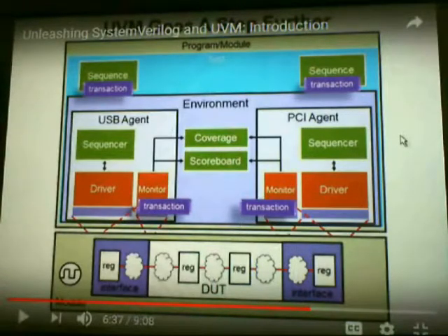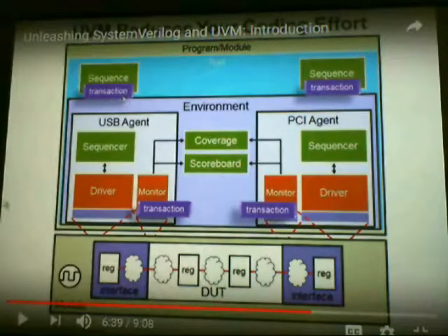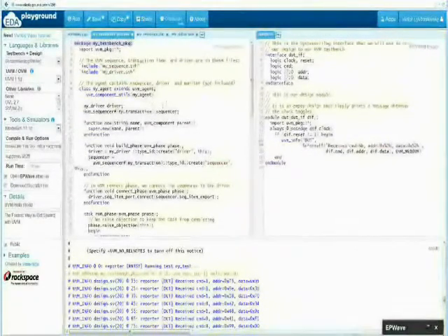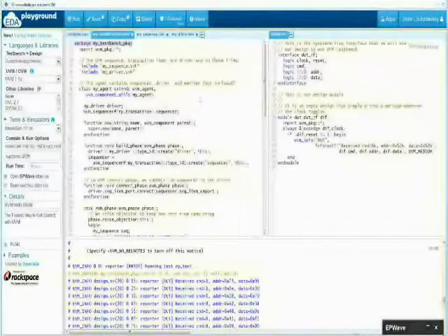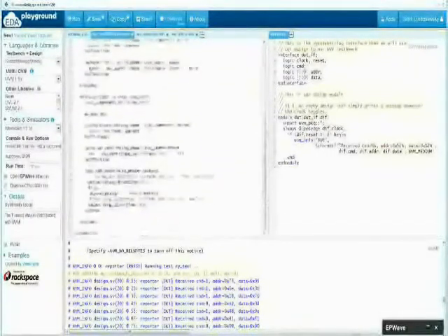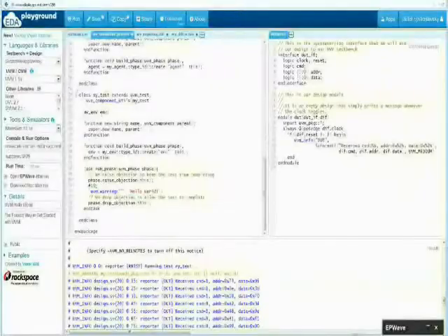Constrained random verification integrates checkers, coverage, and constraints. There are several phases that make up the transaction level communication, message, reporting, end of test, and register layer. It can later retrieve other UVM clocks, and then you can start and run the test as shown in this display. Under the engine: build phase, connect phase, and run phase.